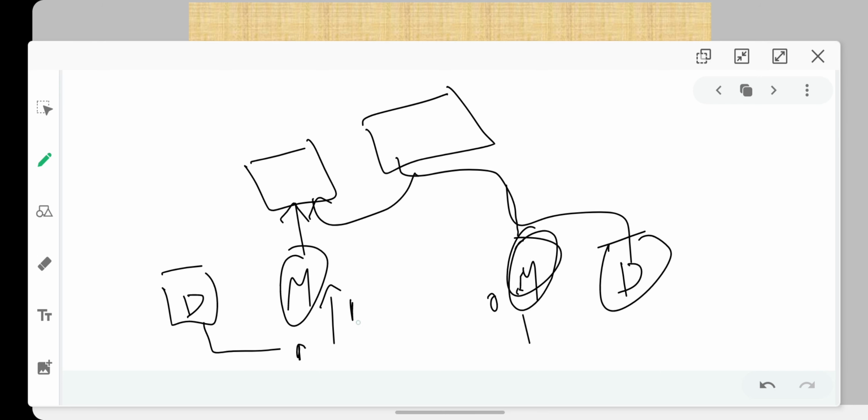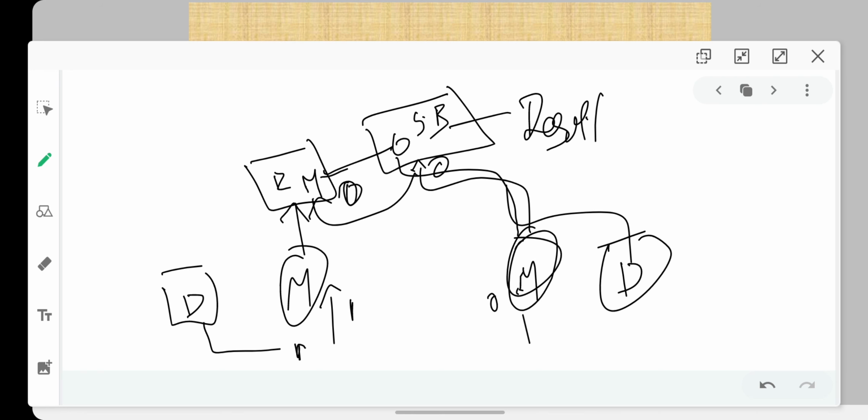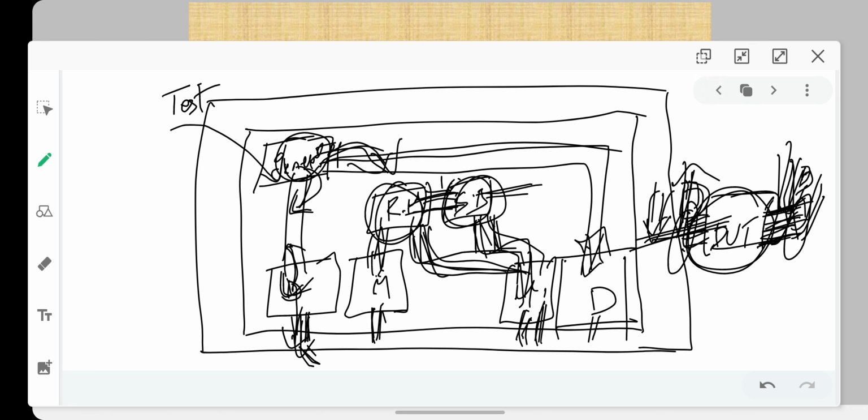Your reference model should also give the same value 0 as the output, right? Since we are mimicking the same behavior of the DUT, and your DUT has given the value 0 as the output, your reference model should also give 0. So both zeros are compared in your scoreboard, and the scoreboard gives the result. This is how the test case is driven, or how the test bench is going to work. This is a brief introduction to the SVTB architecture.